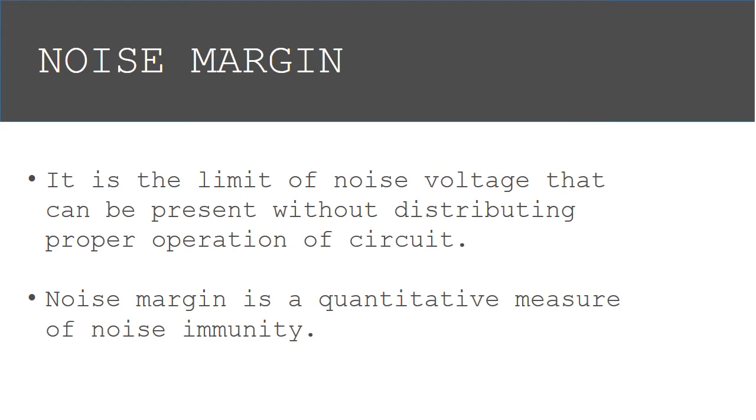Noise immunity is defined as the ability of a logic circuit to tolerate noise without causing any unwanted changes in the output, while noise margin is a measure of design margins to ensure circuits function properly within specified conditions. Sources of noise include the operating environment, power supply, electric and magnetic fields, and radiation waves. On-chip transistor switching activity can also generate unwanted noise. To ensure the transistors switch properly under specified noisy conditions, circuits must be designed with a specified noise margin.